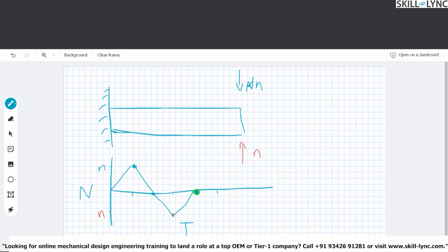And now what happens is the same pattern is followed again. The graph will look somewhat like this. And this is what constant amplitude fatigue loads are. At certain set intervals of time, you have a certain fixed value of load which is acting in a certain direction. As time progresses, the load remains constant, but the direction in which the load acts changes continuously with respect to time.